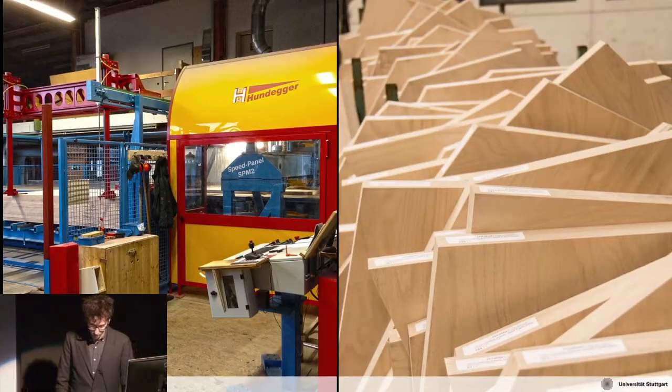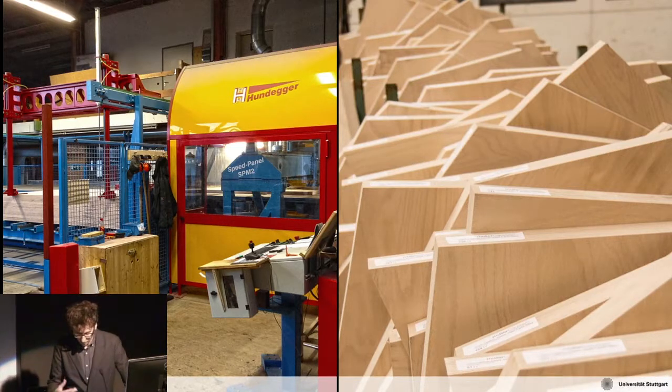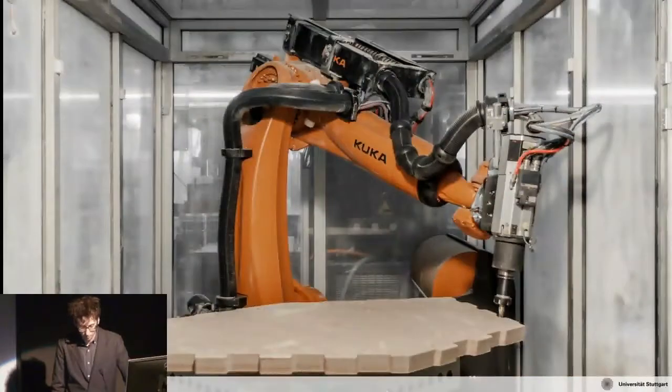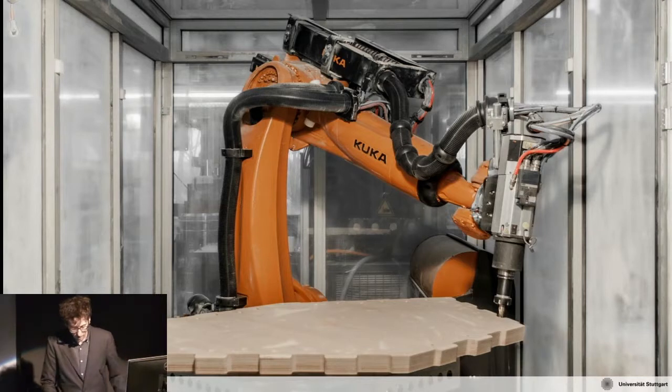This was then in collaboration with the timber manufacturer that we worked with. First of all, they were prefabricated, so they use standard machines in this case. So we looked into what machines they have, what can be used, and how we can enhance it with the robotic setup. So they were pre-cut into stock plates and then mounted onto the robot, also the turntable again, and then milled with super high precision in this case to make these finger joints really have material contact later on site.